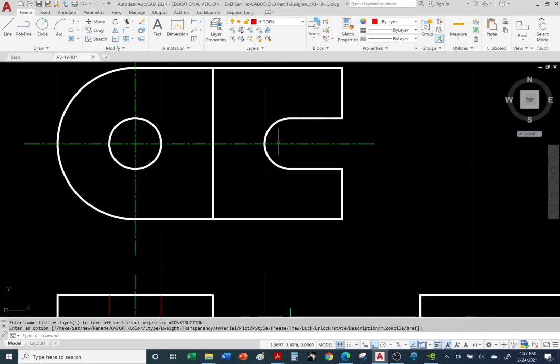Okay, so I deleted my center line here, or vertical center mark. Let me go ahead and bring it back in. Okay, so let's go to the center layer. Use the line command. All right, so you can see I have Object Snap on and I have Ortho Mode on, right? So I can track the center, go slightly beyond, click.